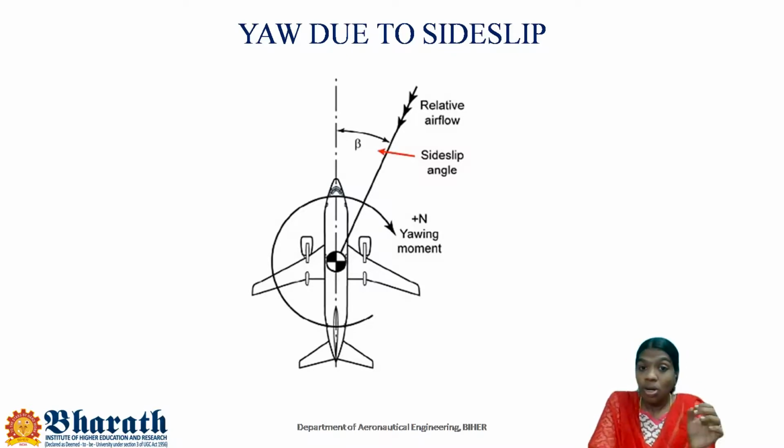So now, what should happen? The aircraft should undergo some rudder deflection, and it should tend to come back to its original position. Now the rudder is going to play a role. You see the rudder should be deflected. The rudder deflection depends on the direction of the yaw. Now the aircraft should yaw towards its right, which means that the rudder should be deflected towards the right.